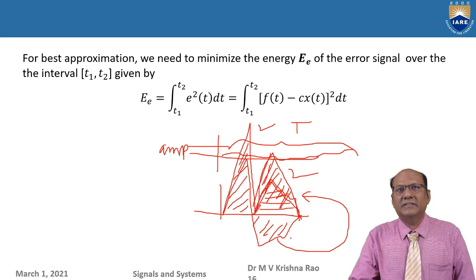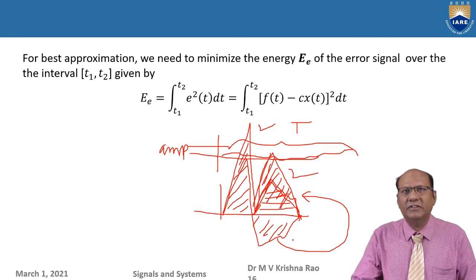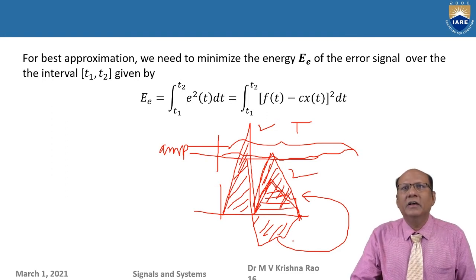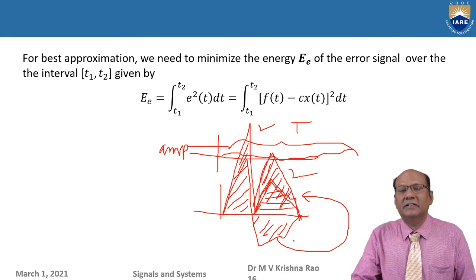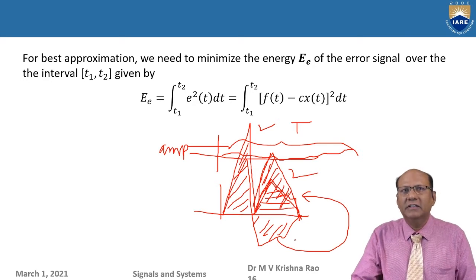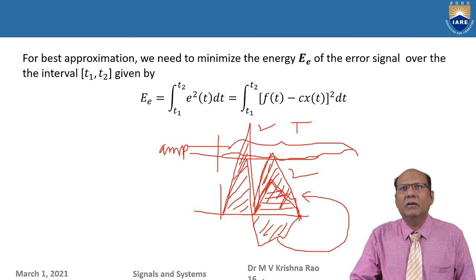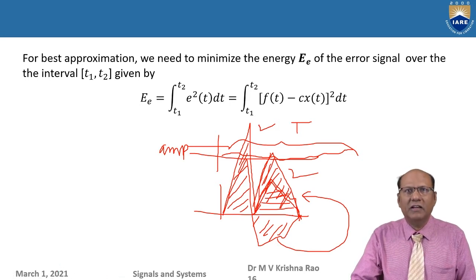And I can call this the size of the signal, the quantity of the signal. So signal is bigger or smaller, how do I define? I can comfortably define by seeing its energy. If the signal has more energy, I can say that the size of the signal, the quantity of the signal is high. Otherwise, the quantity is less. Like that, some kind of quantification, parameterization of a signal we are doing.